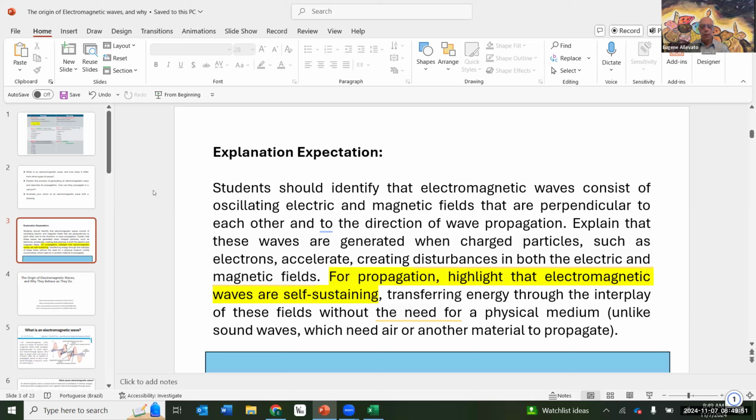So we learn that when we have a fixed magnetic field, like a permanent magnet, and we move a conductor across the magnetic field, a potential will be created on that conductor. And if we have a closed loop, current will flow in that wire. And that is the principle of generators, right?